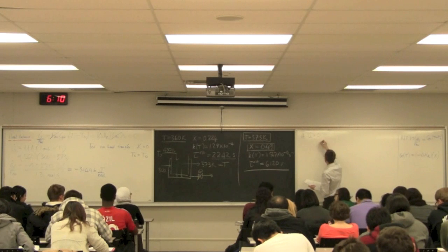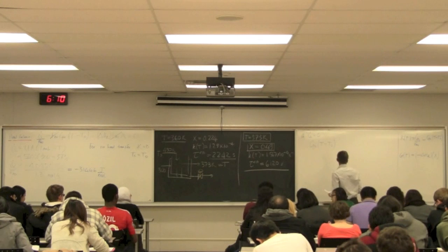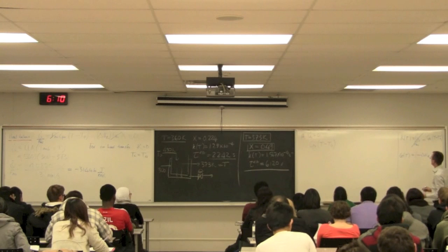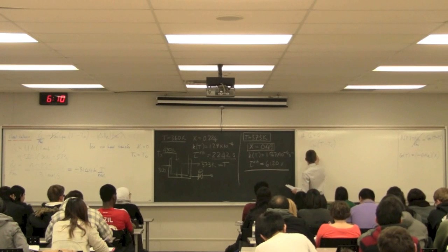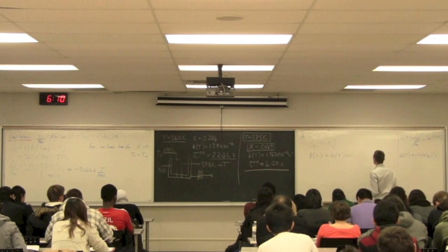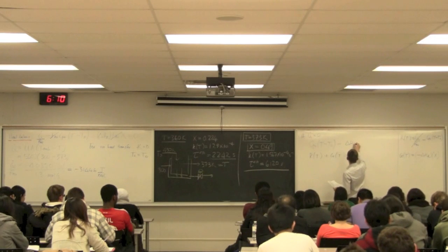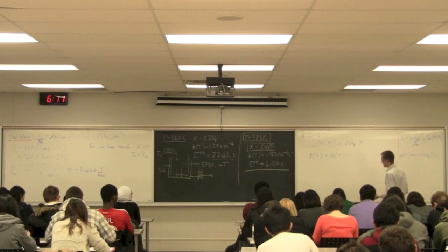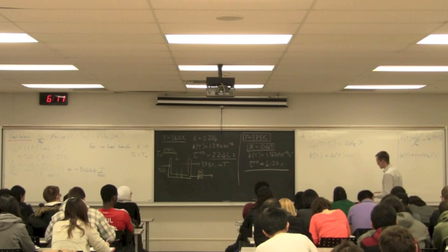So we use our knowledge here. Q naught is equal to 0. We can quite easily find that Cp naught, T minus T naught. Now this term goes away in my R of T. R of T plus G of T must equal 0. So Cp naught, T minus T naught is equal to the heat of reaction times the conversion. So we can quickly solve this and find out what's going to happen to that conversion.